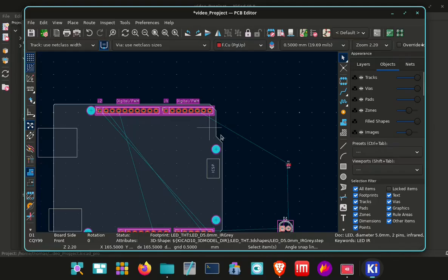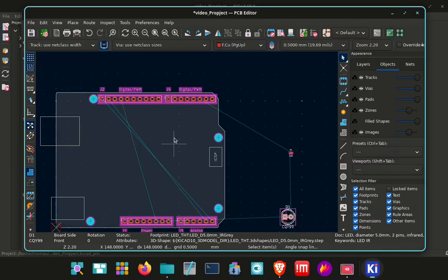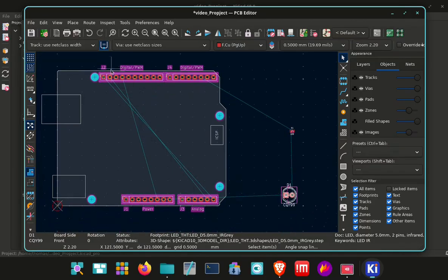So following these tracks, it's important to note these tracks here, this is already done on the Uno. Okay, so ground pins are all connected in the Uno. This is SDA and SCL, and same there. Interesting to note that they swap over direction. So if, for instance, you can't get a circuit on because of the circuit tracks, stick it on the other side of the board, and rotate it or whatever.